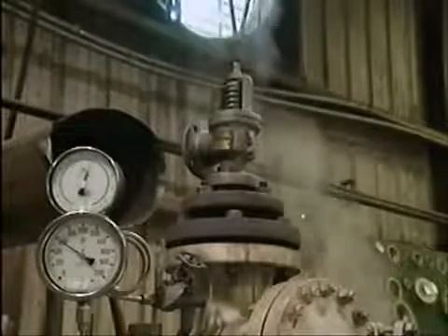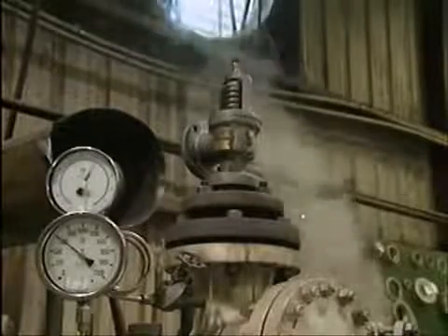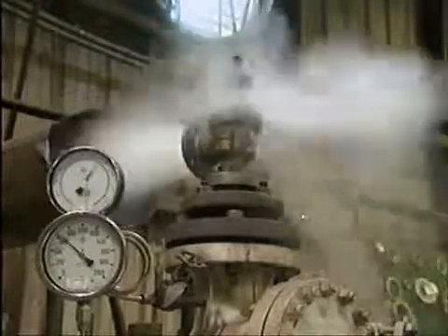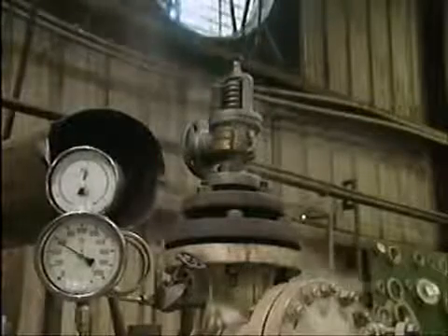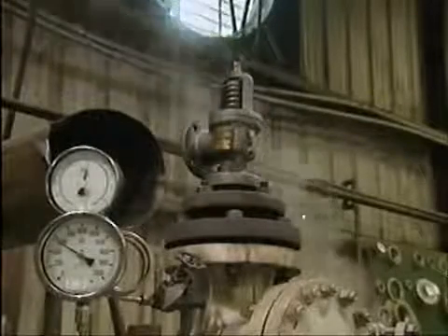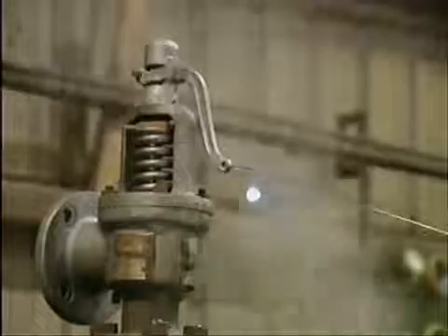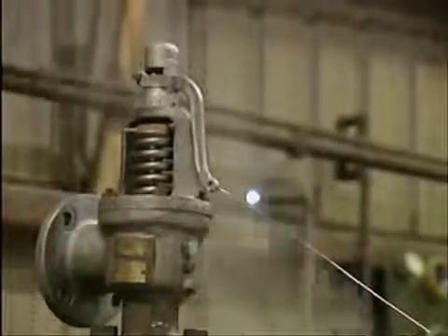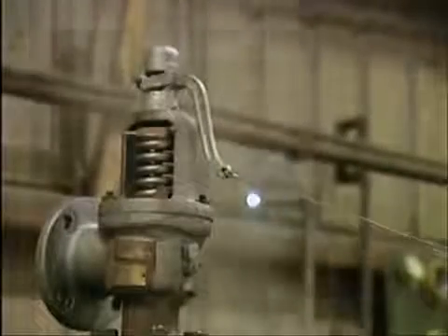An external inspection may reveal that a valve is leaking between the disc and the seat. This could occur if the valve didn't reseat correctly after the last time that it popped. Or it could be caused by foreign matter, such as ash, dirt, or rust particles trapped between the seat and the disc. In many cases, you can correct either of these two causes of leakage by manually lifting or hand lifting the valve. Hand lifting clears foreign matter out of the valve and gives the disc a chance to reseat